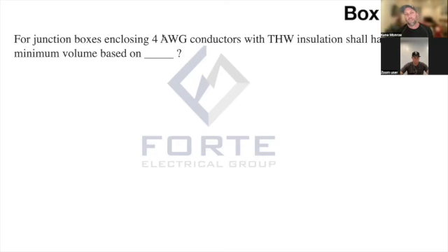Let's just say you're pulling 4 AWG. If you're going from side to side, doing a straight pull through that box, your multiplier is 8 on the largest conduit going into that side of the box.